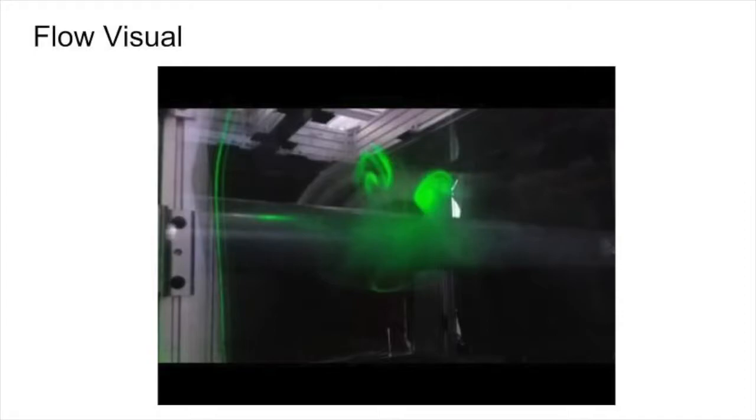Downstream of the separation, the flow quickly becomes turbulent and a broad wake is formed. The wake as a whole is unstable and rolls up into vortices. Because of the separation, the pressure remains low and constant over the rearward face of the cylinder.